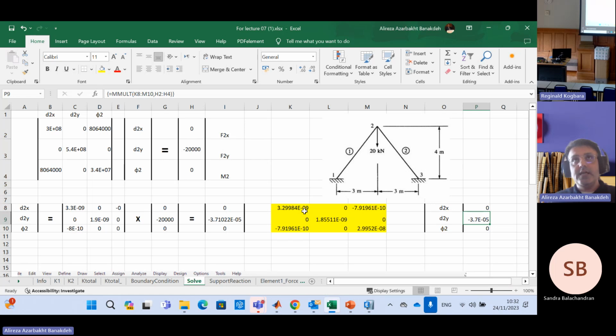However, in this case, because we don't have a deep beam element, Euler and Timoshenko are very close together, but it's not the case in your coursework, especially for that short beam you have. If you go through the Euler theory and Timoshenko theory, you will see some differences, especially when you have a deep beam, which means that the height of your section is significant when compared to the length of your element, your beam.